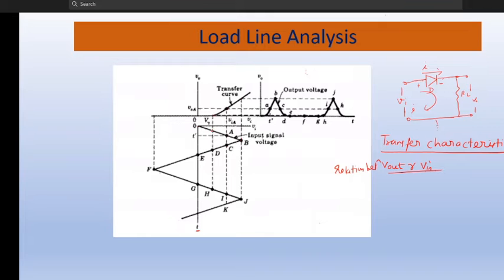You can see that if I consider this portion, this value is v gamma. Below this, once you apply the input, there is no change, there is no diode output, which means current is not increasing. This is the characteristic curve of the diode. But once you increase the voltage beyond v gamma, the current starts increasing.